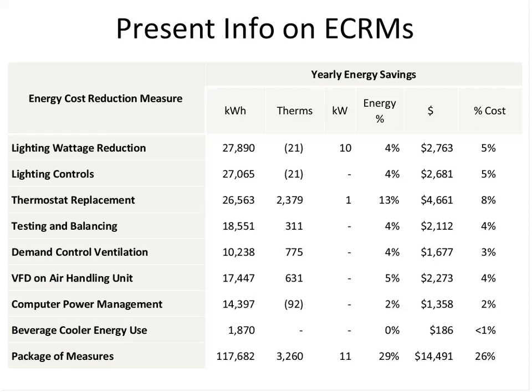And you notice that when we look at the kilowatt hour savings, some of them have a therm savings associated, and some have a negative therm savings. So when you change lighting out, lighting is doing some of the heating load of the building, so you're going to have to heat a little bit more from natural gas. So those are negative numbers.